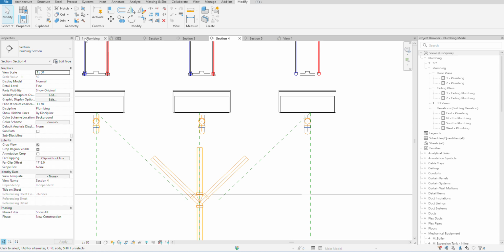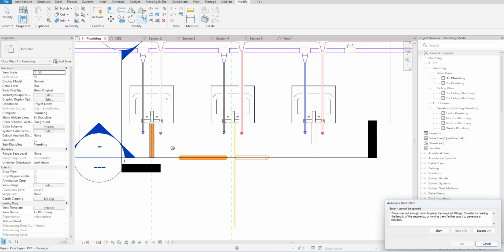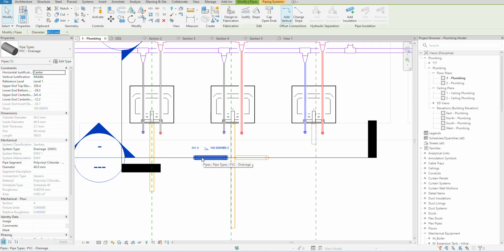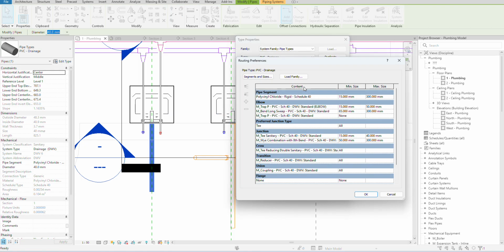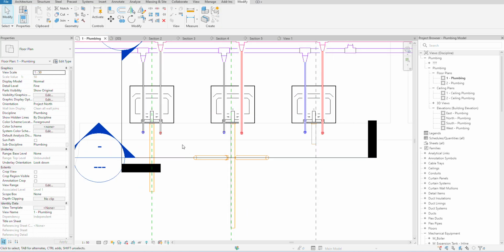Now I will just check if it is possible to trim. We need to change. This is DWV drainage. Now I be good boy and I will make him normal elbow, whichever his elbow is. Just let stand along. Okay, apply. Trim.